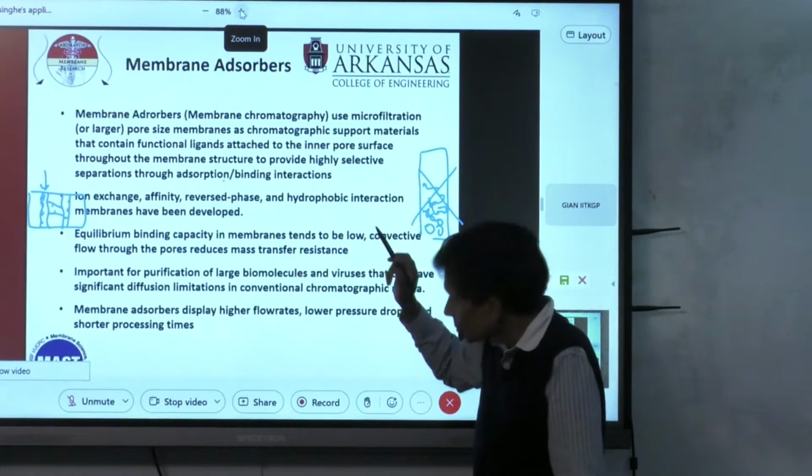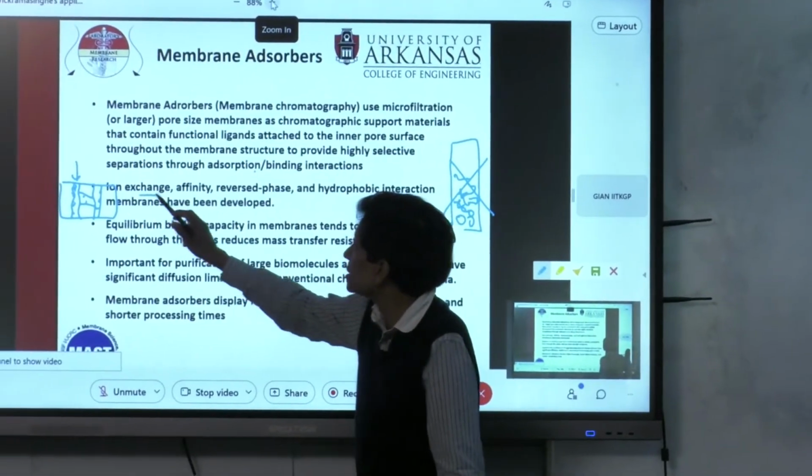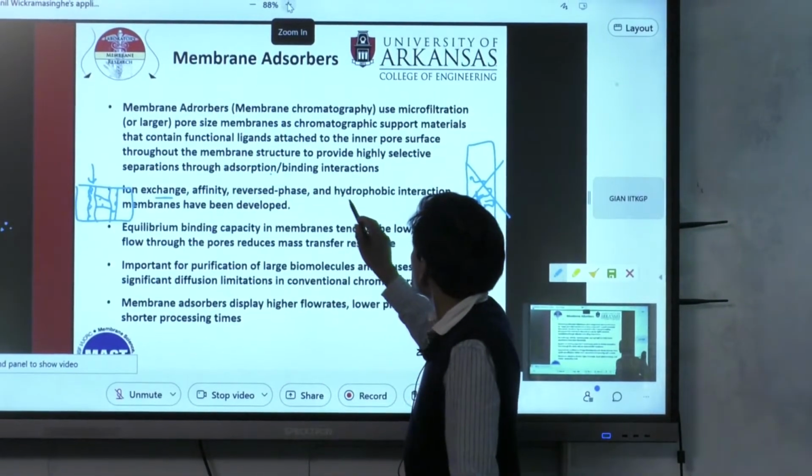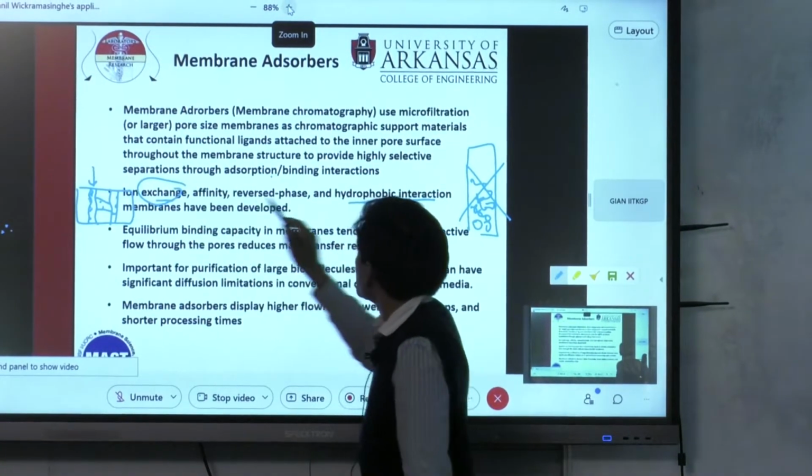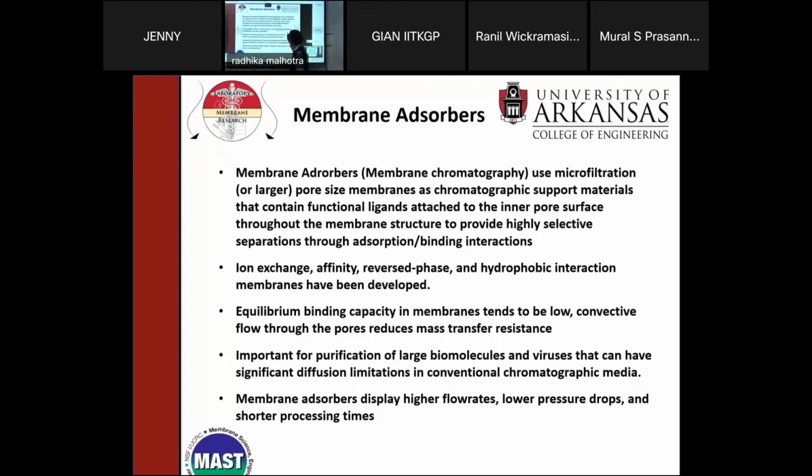Okay. What is used today? We have ion exchange, we have reverse phase, we have hydrophobic interaction. Membranes have all been developed, but basically ion exchange and hydrophobic interaction are the two most common. Okay, they tend to be used routinely in the biotech industry. The others are developing. Affinity binding capacity in membranes tends to be low. Convective flow through the pore reduces mass transfer resistance.